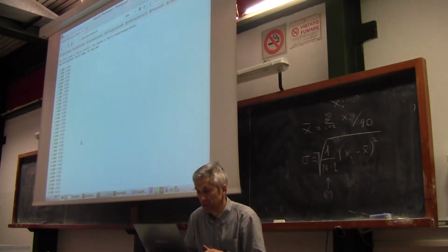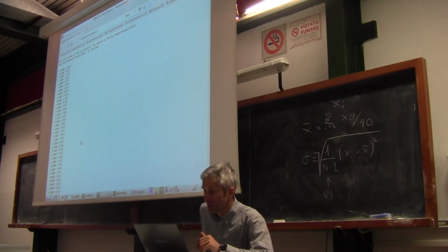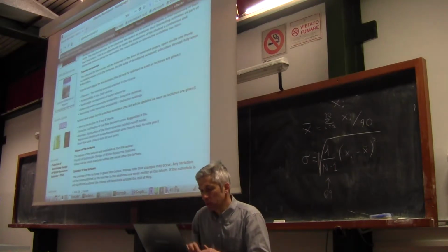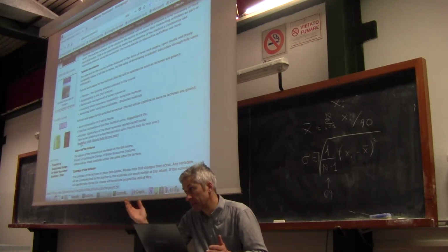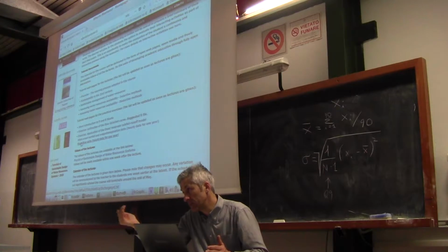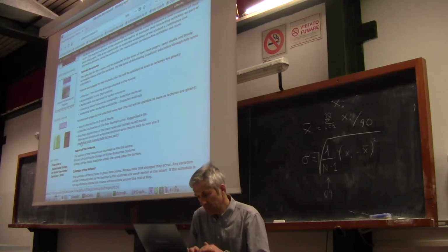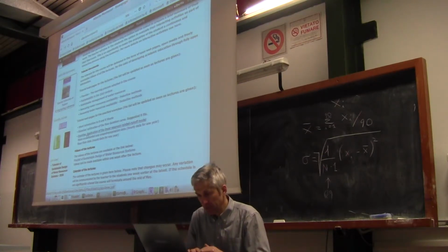This is the file. If you click on it, you see that there is written, the first column is hourly rainfall, the second is hourly evapotranspiration. And you may forget about evapotranspiration, second column. And also there is a column of river flow data. The river flow data allows you to compare the output from the model to the corresponding river flows. It's not needed, the river flow data, for running the model. It's needed for comparison.